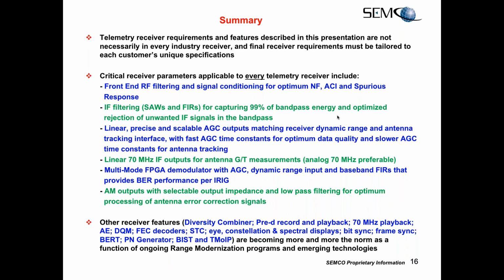Another question here. Can the BERT test signal be routed out to the system? Say, for example, using the BERT in one receiver to do a BERT in another receiver? Yes. We have an option that you can put into the receiver for providing an external input to the embedded bit sync. So by providing an external input to the embedded bit sync, you can basically bring an external signal in, an external TTL clock and data signal or analog signal in from another source, and use the embedded BERT to do your BER. Okay, great answer there.